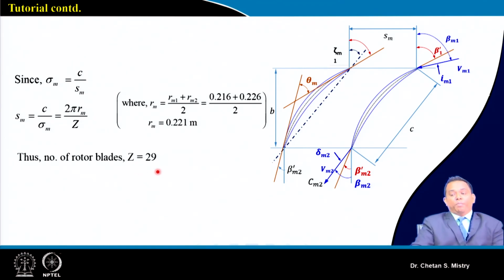on the hub, because suppose we have a small hub diameter, and in that we are planning to fix more blades, or the number of blades is coming out larger, it may be very difficult for them to design the slots. Okay, suppose you are considering a blisk kind of configuration, there, in order to do machining, it may be possible that the tool may not go inside. So here also we have a constraint.